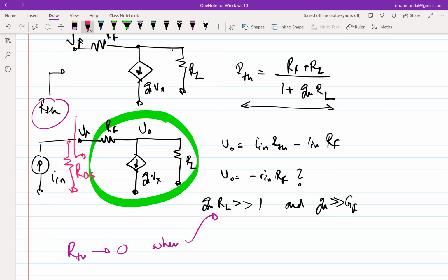Okay, so anywhere you will see that I want to push in a current, you would like to ensure by design that the block you are pushing the current into behaves somewhat like a virtual short. Obviously in real life you will not be able to get an exact short, but the condition you have to meet is that the input impedance looking into that block has to be much, much lesser than the impedance of the source that it is driving.